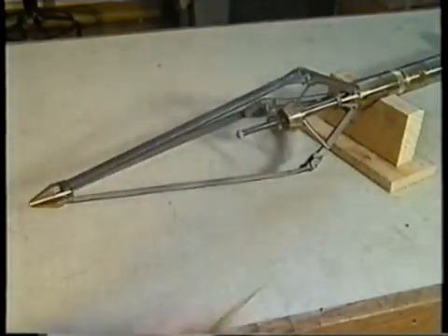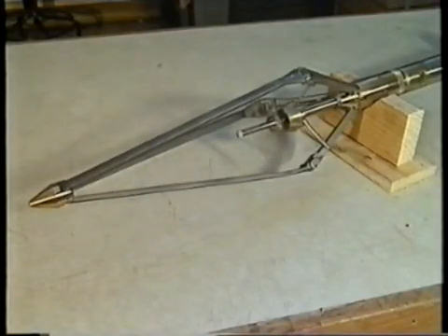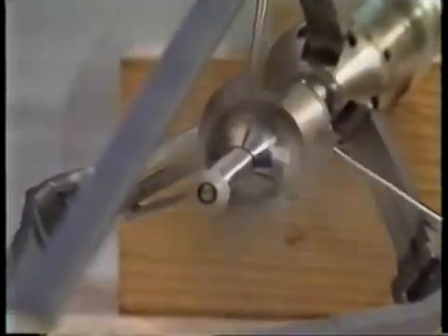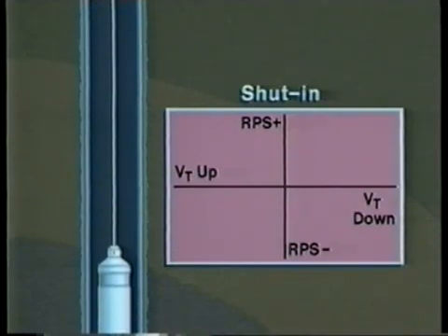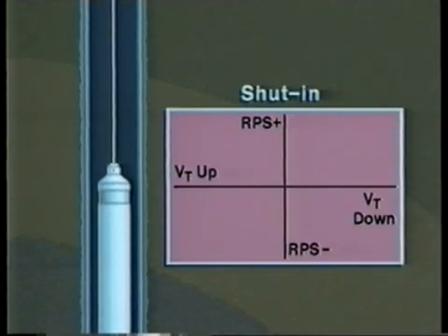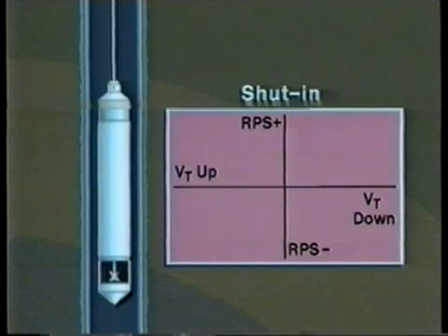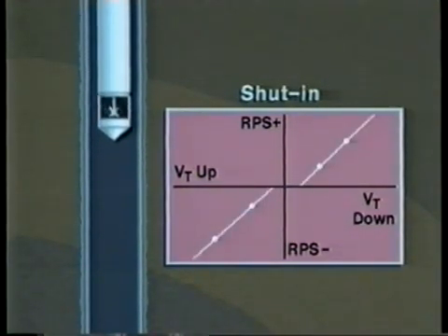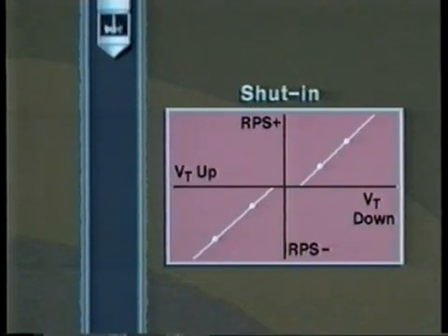Flow meters respond to the bulk flow rate, even in multi-phase flow. A turbine or spinner rotates as a function of the rate at which fluids flow past it. If the spinner response in a static fluid is plotted in revolutions per second for several logging speeds, both up and down, the relationship is linear. The lines do not, however, go through the origin. The cause of this shift is the viscosity of the fluid. Greater viscosity tends to cause a greater shift.